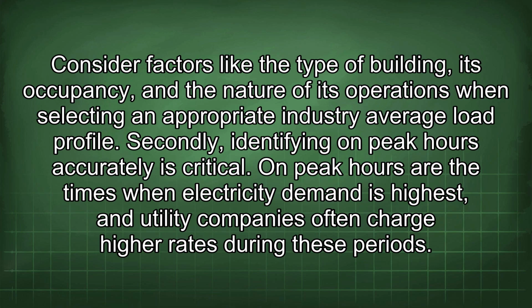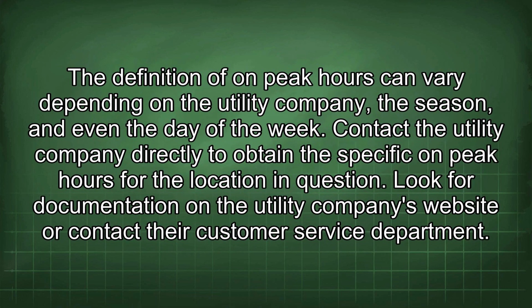average load profile. Secondly, identifying on-peak hours accurately is critical. On-peak hours are the times when electricity demand is highest, and utility companies often charge higher rates during these periods. The definition of on-peak hours can vary depending on the utility company, the season, and even the day of the week. Contact the utility company directly to obtain the specific on-peak hours for the location in question.